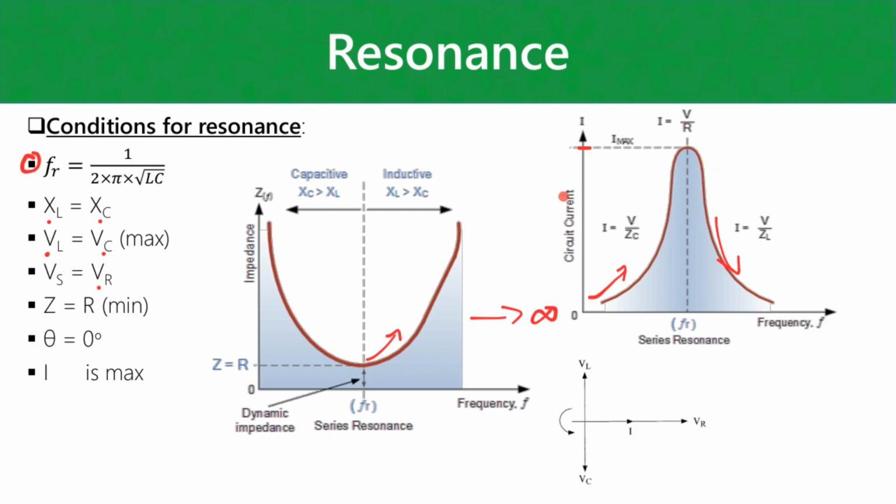If you were to change the current on the y-axis to a dB scale and take the -3 dB point, we're going to have a bandpass or band select or frequency select filter. So you get something like this. I'll explain in a moment. This ties in with things like bandwidth and selectivity.